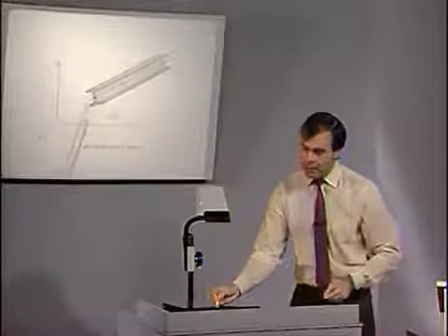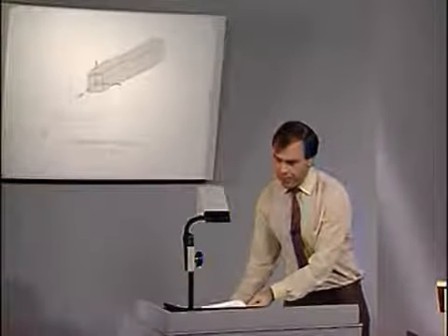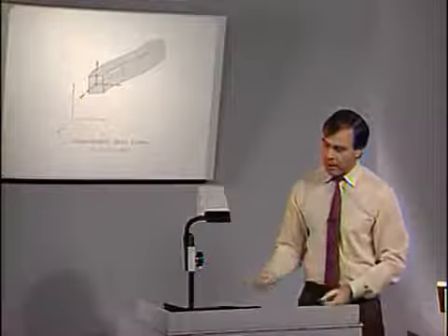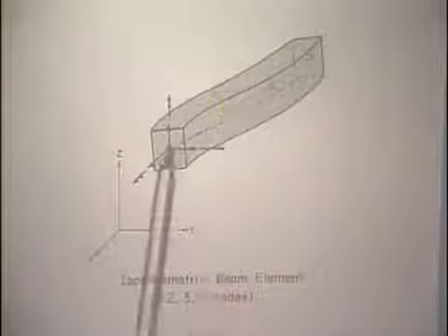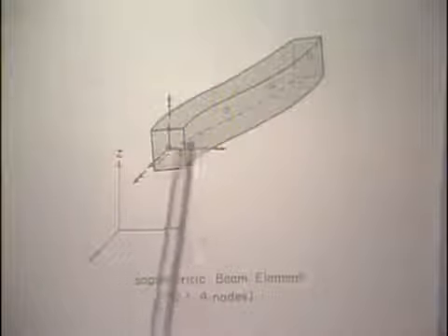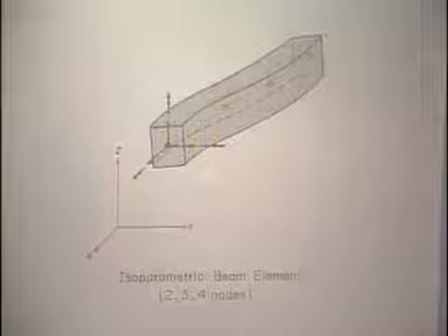Then also a beam element, a 2-node beam element, Hermitian beam element, and the isoparametric beam element that we talked about in the course. This element can be used with 2 nodes or 3 nodes or all 4 nodes.